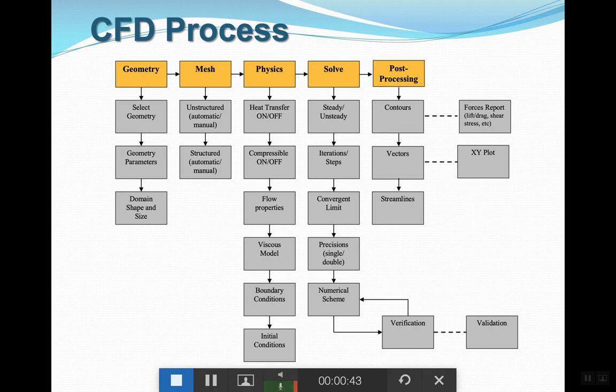geometry. The second step was basically mesh generation. If you remember, we have one big control volume, but since we have developed our equations based on the assumption of infinitely small differential size control volumes, now we have to divide our big control volume into small pieces, smaller control volumes, differential size control volumes, which we call cells, then solve our equations over every single one of those cells. So we covered these two steps.